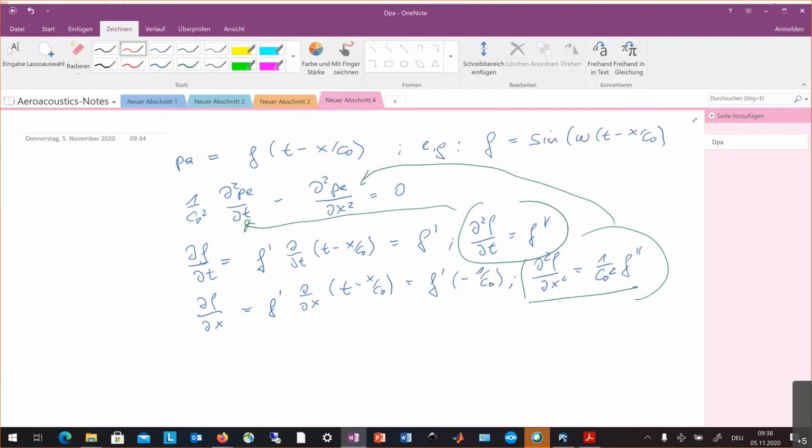And what is important here is that you do not have any decay in the amplitude. Where is the decay? There is no decay in amplitude. And that is also the case in practice: when you have such a plane wave in a pipe, the decay is negligible. When you have a very long distance, then our model is not correct, because then we have also to take into account a little bit the damping of the air when waves are propagating.